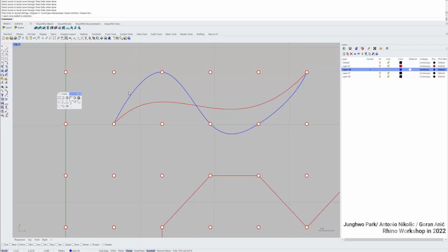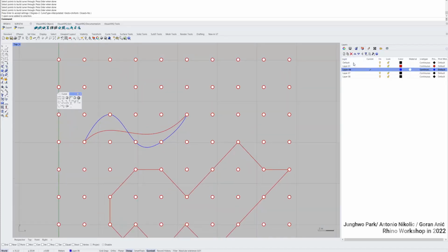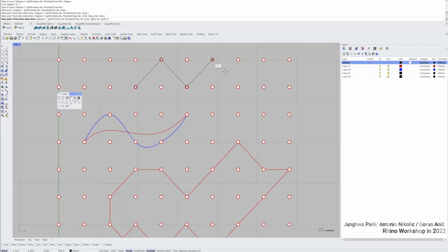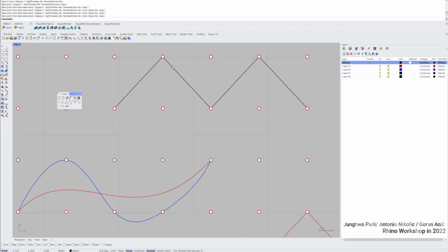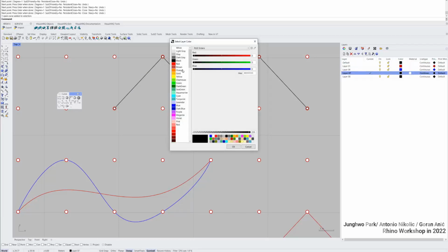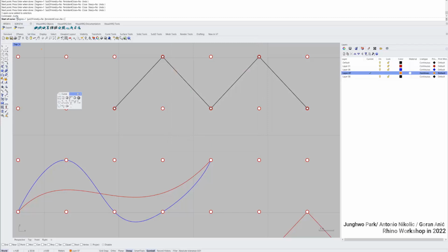Yeah. And I'll put in another command again. So let's go with the first, left one. Click on control point curve. And there is a degree. So if you put the degree to 1, basically this is the same as a polyline. That's the degree 1 curve. And if you do the next, second degree, I'll change the layer to orange. And degree 2, I'm gonna go through exactly the same points. And as you can see, this is a degree 2 curve.